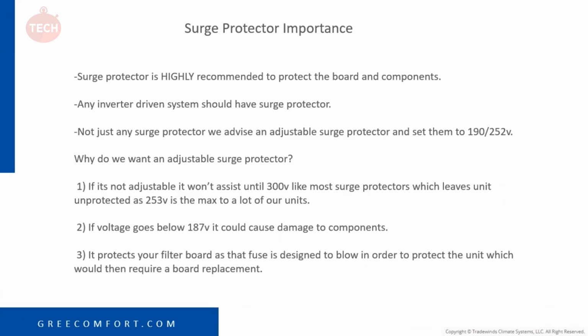Again, because if it goes below 187 volts, that's the lowest the unit can have for input voltage. That could cause damage to the components as well. So again, an adjustable surge protector is recommended.